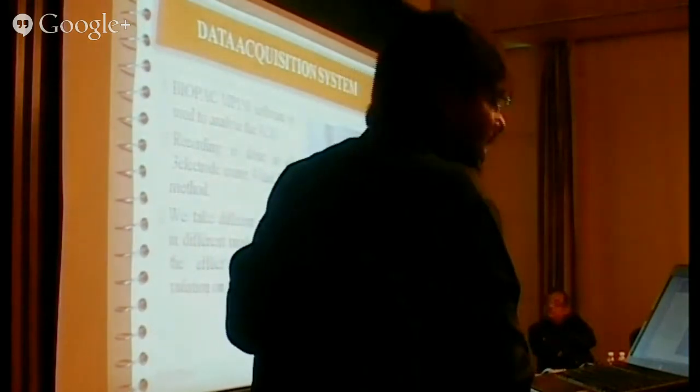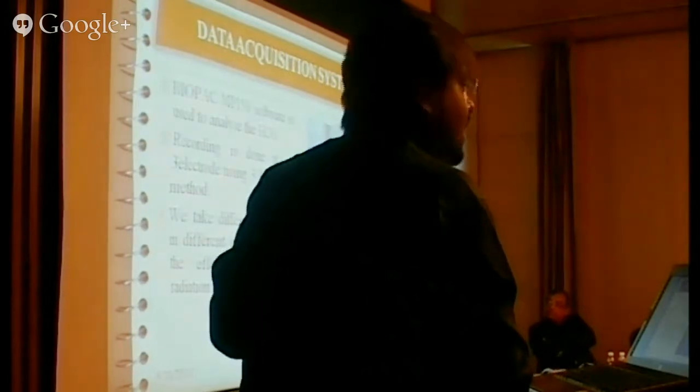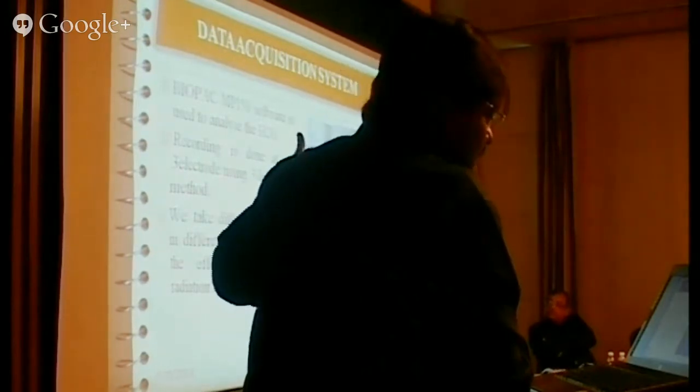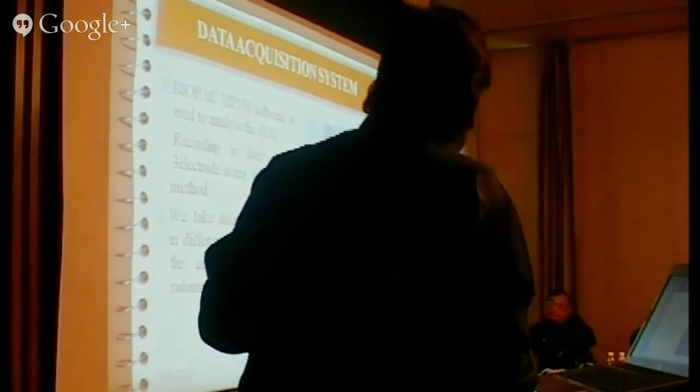Data acquisition system: we are using the BioPac MP150 system in our lab to collect and analyze the ECG signal. With the help of a 3-lead ECG, by attaching 3 electrodes on the human body, we take different parameters in different modes and check the effect of the radiation on the human heart.